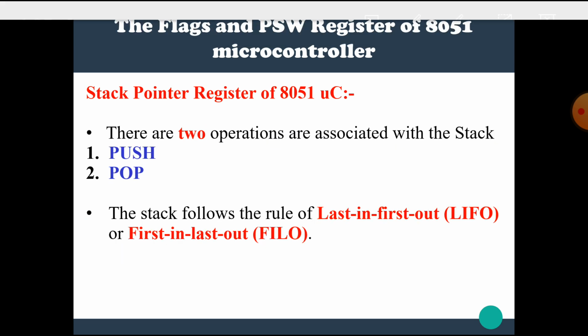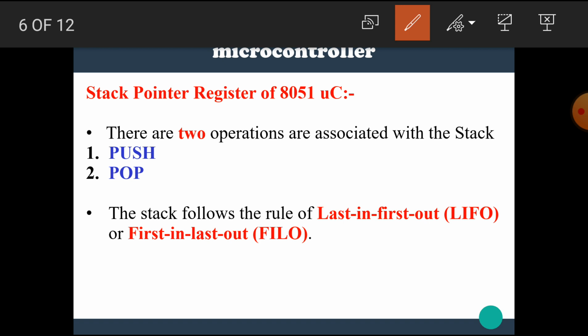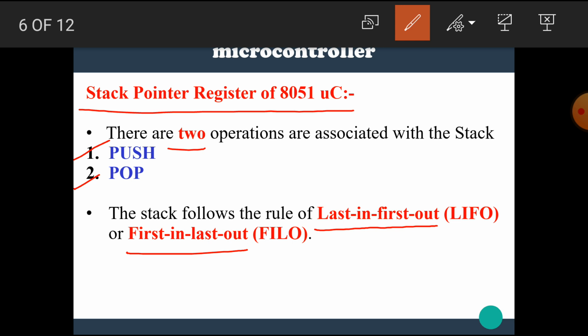Now, next, regarding the stack pointer register of the 8051 microcontroller, there are two operations associated with the stack. The first one is the push operation and the second one is the pop operation. The stack follows the rule of last in first out, or first in last out. I hope you all know what is meant by last in first out. Let's take a short look at last in first out.